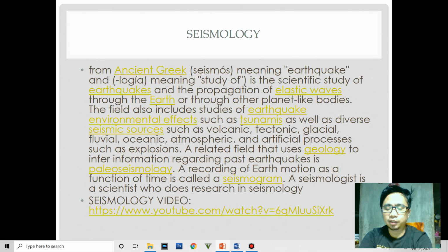So that is why, again, seismic research in engineering is of major concern for us to control the damage. Okay, we cannot really prevent the damage, but we can control it through the aspects of seismology, in particular the energy dissipation. We are going to design our structures considering this energy dissipation. So you might want to consider what is the most active fault nearest to your site.